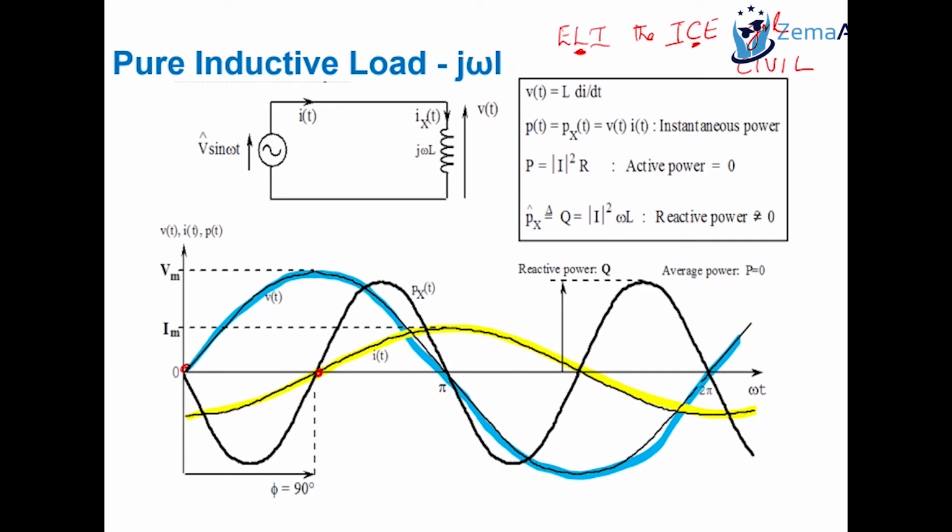Sometimes you may see, when you did transformers, there's a primary and a secondary. You can draw the whole phasor diagram for the currents and voltages in a transformer, but you need to begin with one voltage as your reference, and usually it is the voltage on the side which is connected to the load. So if the secondary is connected to the loads, that secondary voltage will be your reference voltage, and then you start drawing everything.